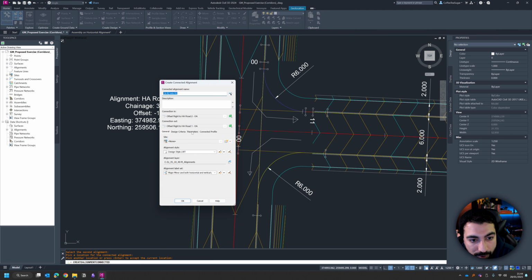Then I go to parameters. It's a circular fillet and radius is 6. Offset is 0. If I do offset as 1, and let's do this one, you can see the offset is from that point outwards, so from the 6 meter offset in. Well, I don't want any offset at the moment, so it's 0. It will be right there. So basically using these two alignments, if I'm going to do a circular fillet with a 0 offset and a radius of 6, that's where it will appear.